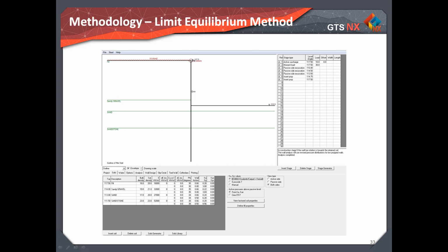The pile geometry and the soil profile of the case study are inserted into the program, followed by setting up the construction sequence as discussed before. In addition, various other soil and design parameters are also input to the program, including prop Young's stiffness modulus, prop spacing and length, analysis options, and so on.